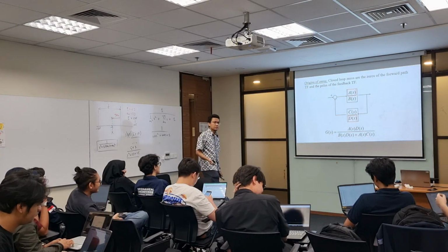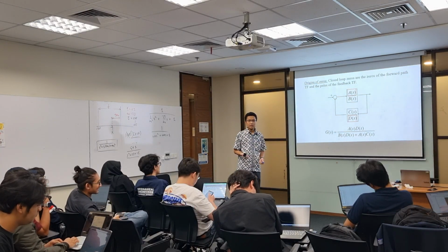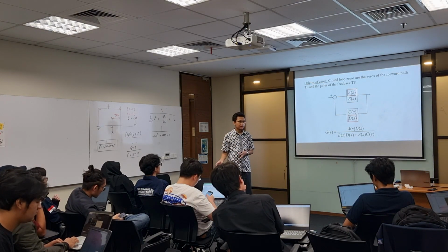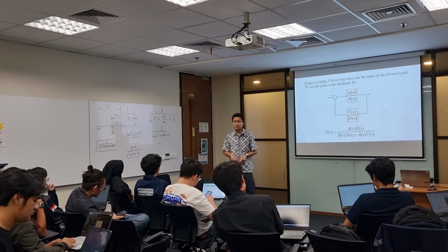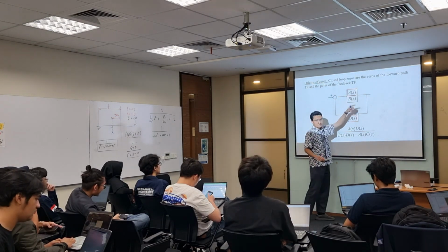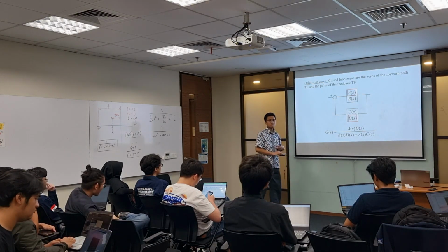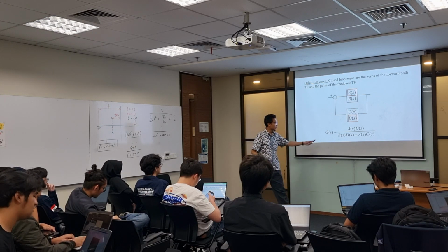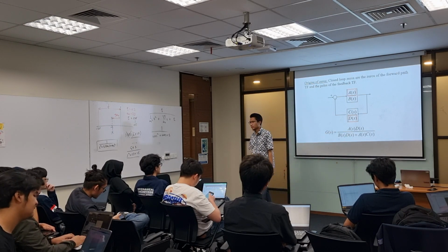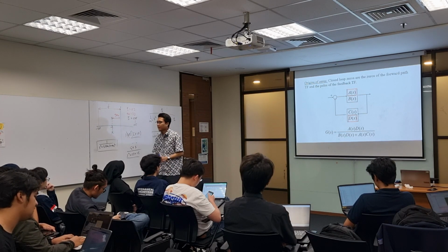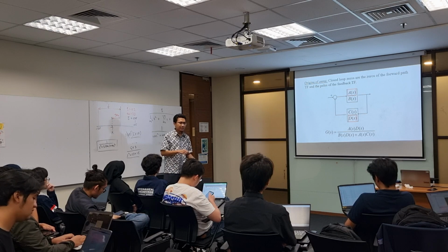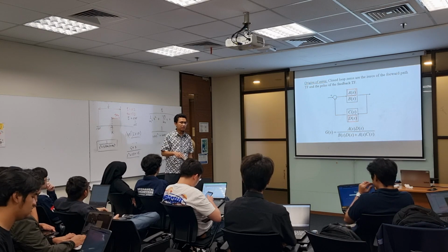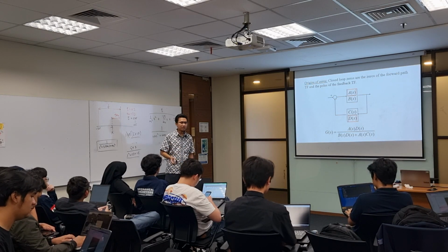Yeah, one thing that you cannot change is that if let's say your plant has a zero on the right hand side, if your plant itself has zero on the right hand side, then the A over here has the root on the right hand side. You cannot avoid that. Yeah, clear? Then as a result, this will happen on the right hand side. So normally a system that behaves like that is because of its inherent model. Because the model is like that. We cannot change the model.